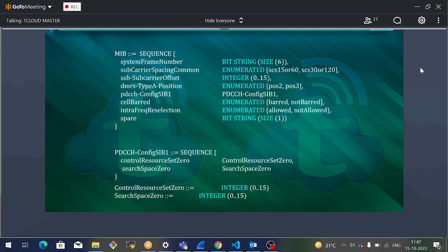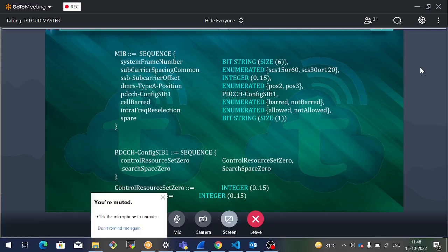It gets all the symbols, 432 symbols. From that, it will extract 864 bits. It will throw away the coding bits. It will remove the CRC. It will do all the things. The total number of bits available after extracting is 32 bits. In the 32 bits, the mobile knows that 24 bits is the MIB that must be decoded by using these rules